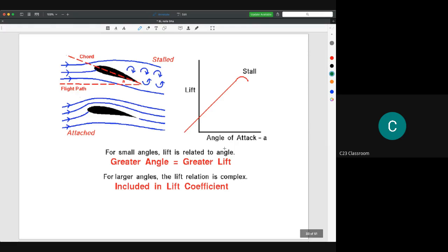So this is another figure that I could get. So why do people need to have a very good streamline? Because to make sure that the flow is not detached, there is no separation. So when the angle of attack becomes bigger and bigger, the separation starts to occur, and when the separation starts to occur, the stall occurs, so it will make the lift force drop immediately.